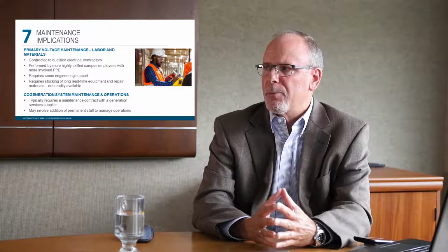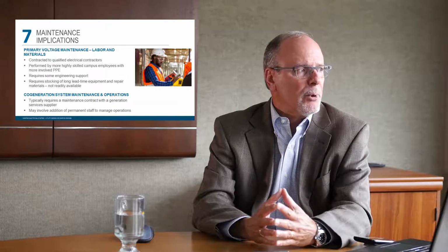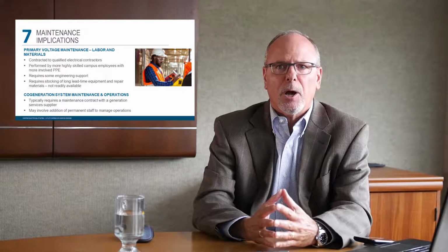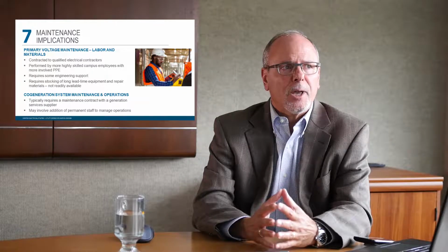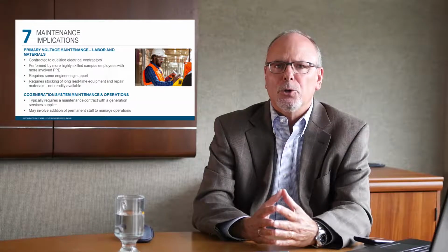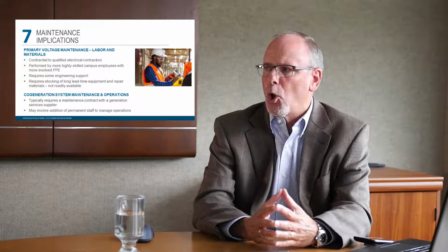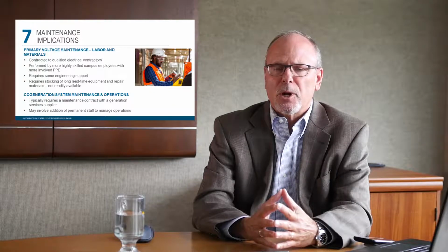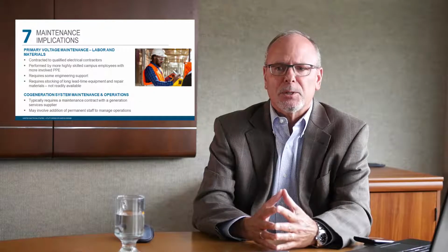These systems do require some level of engineering support. Larger campuses sometimes have these folks on staff. Most campuses hire out these services to consulting engineering companies. The other thing you have to look at in maintaining a system like this is that the parts and pieces for it are not readily available at the electrical supply. So you do have to have stocking of some long lead time equipment. And you also have to keep some transformers and switchgear just in case, because they are kind of hard to come by in an emergency.